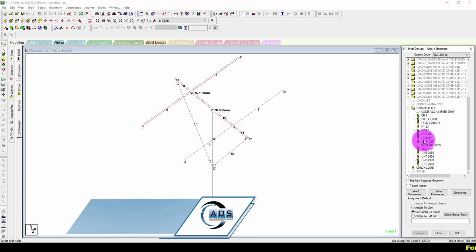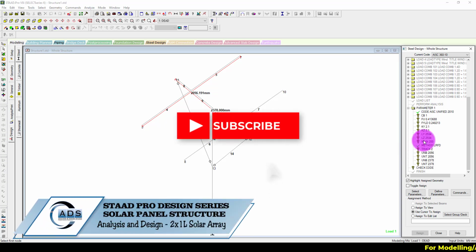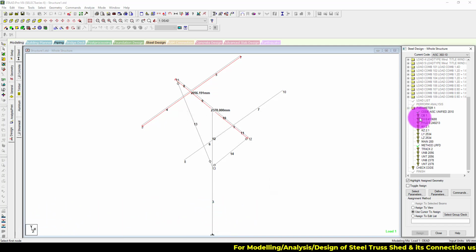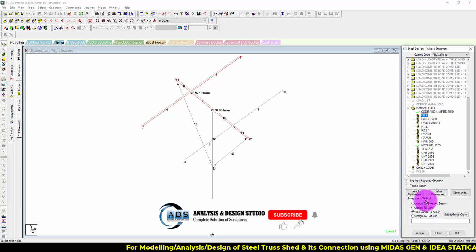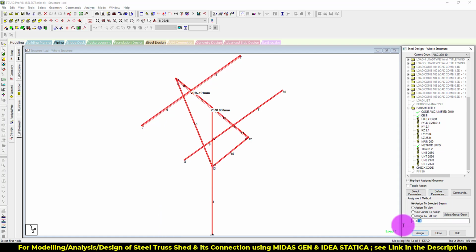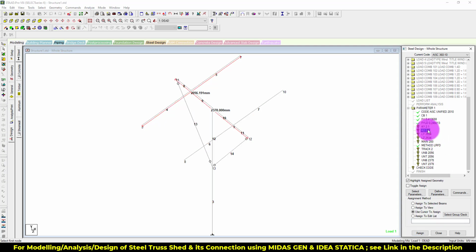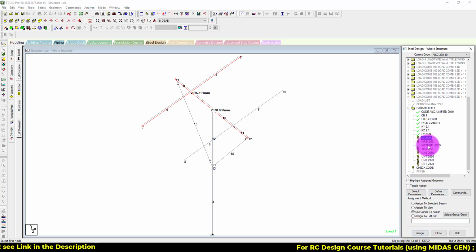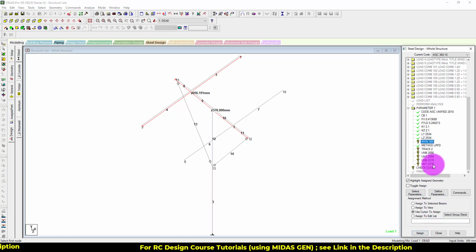Now it's time to assign those parameters to the respective members, because there is a question mark displayed with these parameters. CB I require for all. FU for all, just copy paste the beam numbers here. KY and KZ: KY for 3 and 12, KZ also for 3 and 12. LY and LZ for 3 and 12. Right? Main for 3 and 12. Further for 13 and 14.